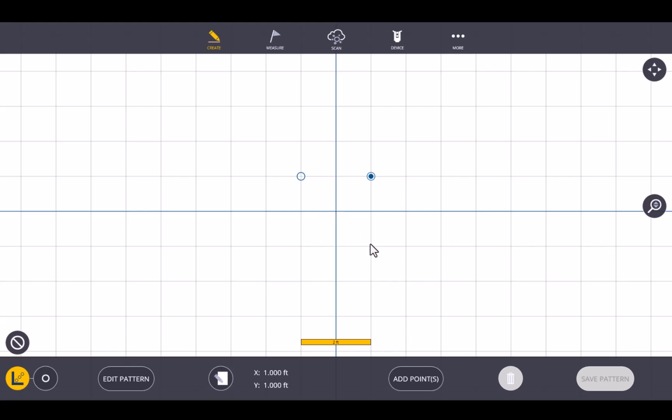If we would go down vertically, that would become a -1 y. As you can see, each of the intersections I clicked on is at a 1-foot increment. However, in our example, we need to make it 6 inches by 6 inches off of our center, so clicking on these intersections will not work. Let's hit our clear button and start from scratch.